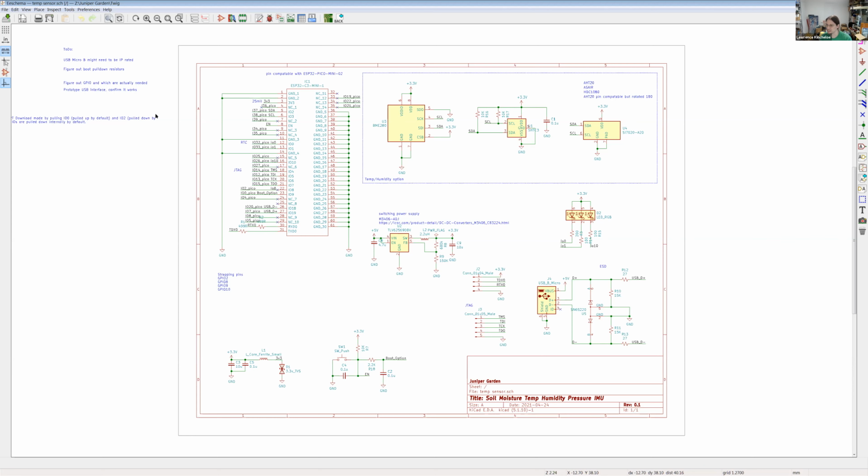So it's a pretty simple design. It's got an RGB LED on it. It takes in 5 volts from the USB plug, and level shifts that down to 3.3 volts. I think at some point we're going to do a battery powered version of this. But for this initial product, we're looking at just the bare minimum, get out the door kind of price point. Even at this point, the device in total is probably going to be like $25, $30 per device, which is higher than I'd like, but prices are not kind for small volume products like this.